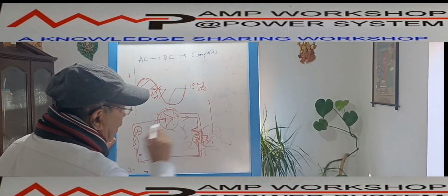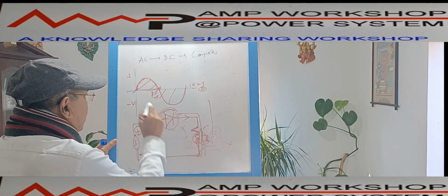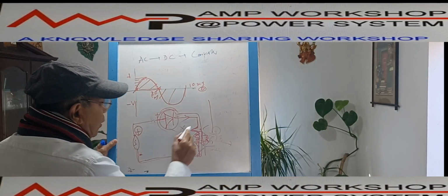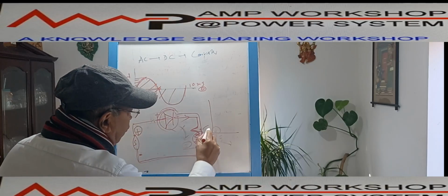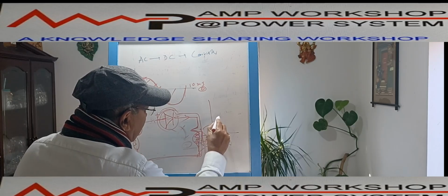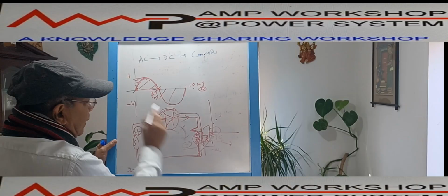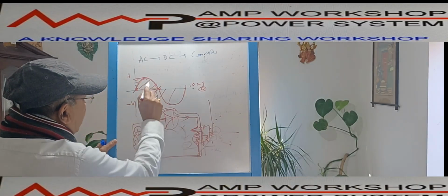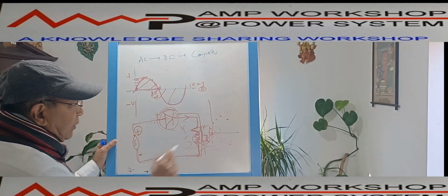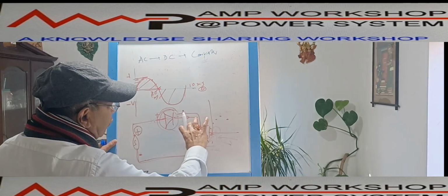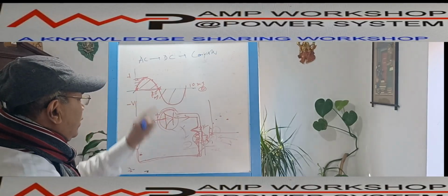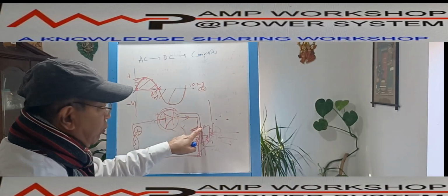The same voltage will appear here. Suppose the input goes 1 volt, 2 volt, 3 volt, 4 volt, so it is increasing. The output voltage from 0 seconds is first 1 volt, then 2, 3, and then 4. When the AC is at 4 volt, the voltage here is also 4 volt. Then the voltage comes down to 3 volt, so the voltage comes down here too. I am plotting the output voltage across the load, across the lamp, considering the diode has no resistance. The same voltage comes over here.